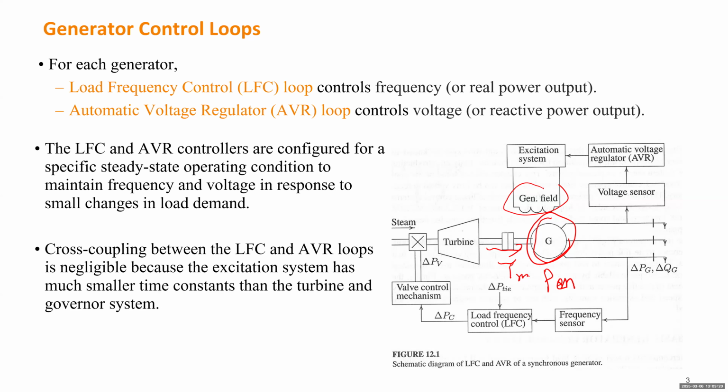But if you want to simulate stability of the system under large disturbance, those two control loops will interact. So eventually, you have to consider the effects of both loops to judge the stability. A better practice will be to model the voltage control loop and frequency control loop accurately and do time domain simulation, which will cover both subtransient and transient dynamics.